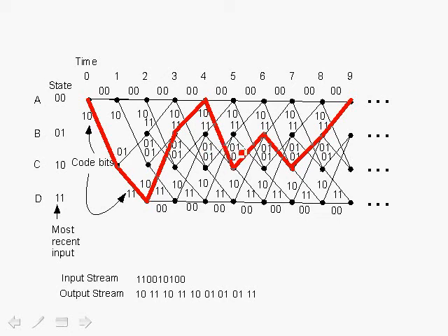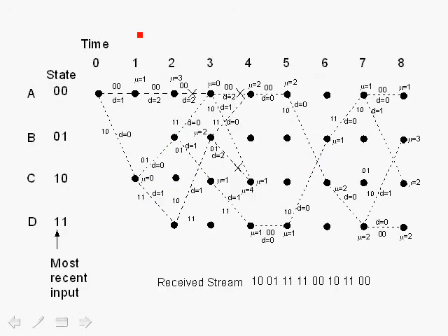So increasing the constraint length increases dmin, and therefore the error correction capability. We'll show some simulations that verify that point later on. We will now discuss Viterbi decoding, which is a maximum likelihood decoder for the convolutional encoder. It is optimum. It is an iterative procedure and simplifies quite a bit the decoding of the convolutional encoder. And for this reason, it is used quite a bit in industry. In fact, it is one of the most predominant decoding algorithms used.